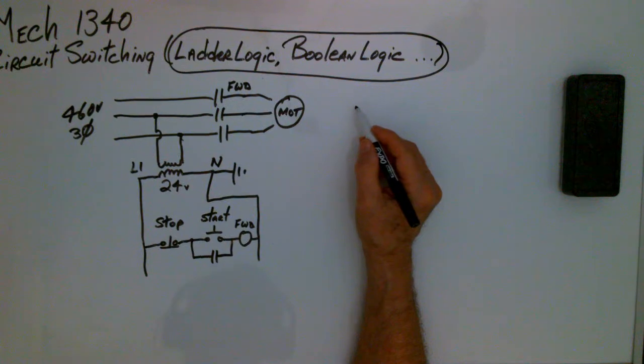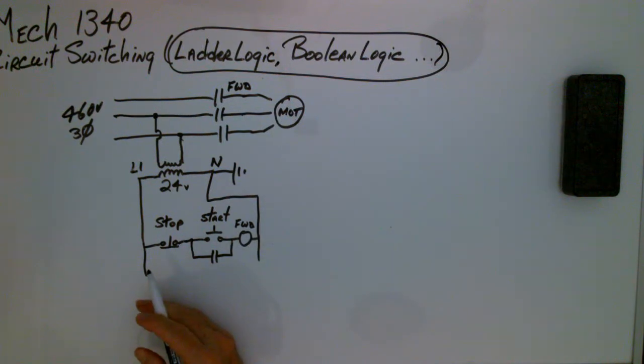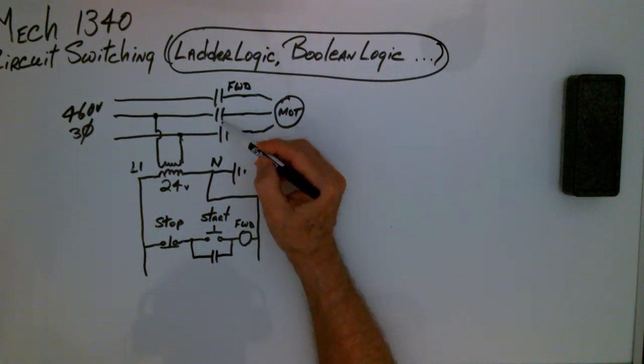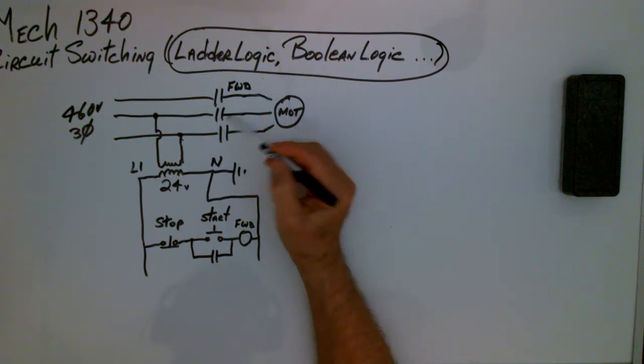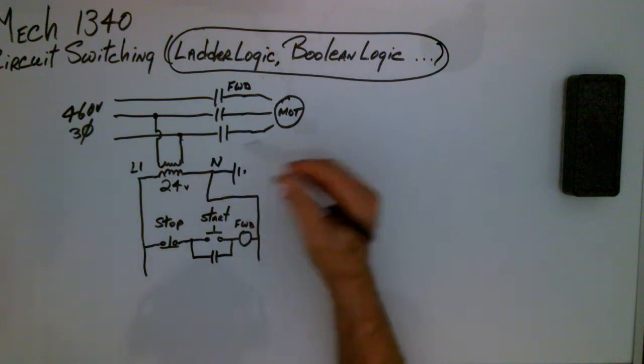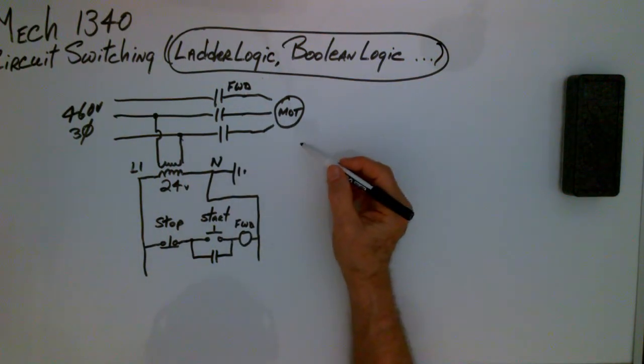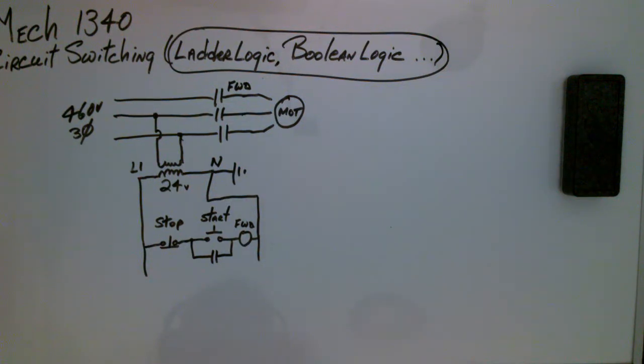Okay, so whenever this coil is energized, okay, by our circuit down here, these three main contacts will close. When they close, okay, the motor will start. And we've assigned it a forward direction, so this has the same name. No confusion there. So here's what we can say about the logic down here in the control circuit.